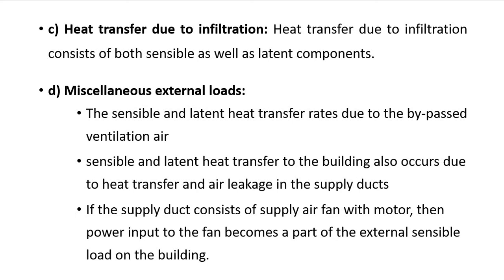And for supplying air as well as for absorbing air from the space, we are using supply air fan as well as return air fan. So these two fans are working with the help of motor. So when the motor is operating, there will be some heat release. That also has to be considered while calculating the external loads.